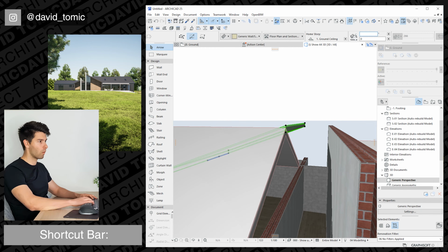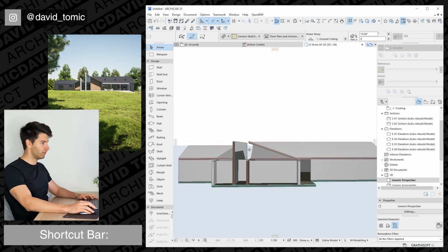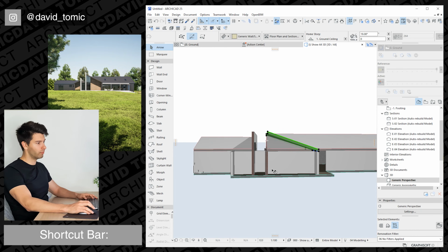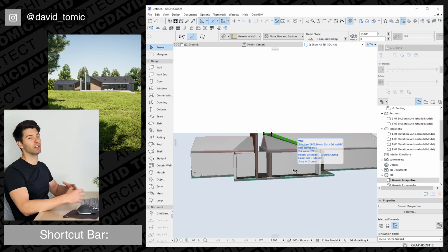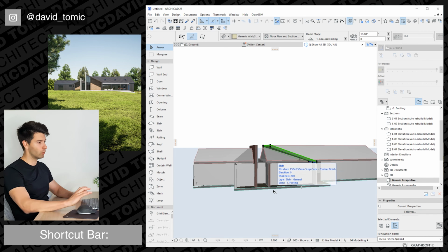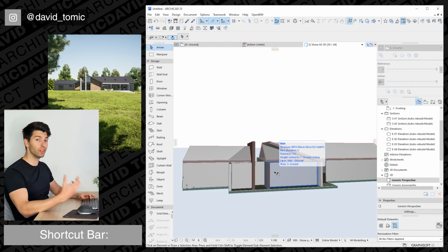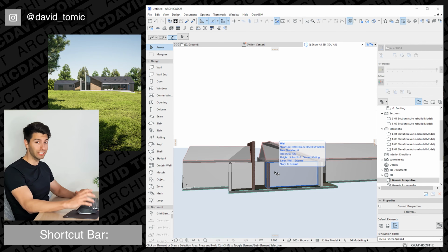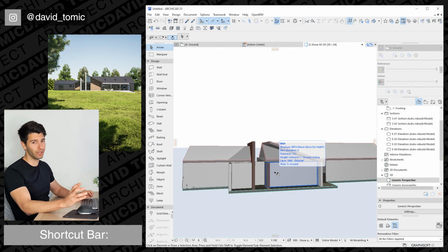And if I drop that 1 more degree, let's call it 19 degrees, that'll be a near perfect connection at the top. We would obviously do that in actual roof pitching degrees instead of just randomly selecting. But for the purposes of this, knowing that it's going to go everywhere around the world, there are all sorts of different construction standards that it would be just way too hard to get into. So we're just keeping things relatively generic. Make sure that you apply your construction guides, your construction knowledge, and your industry regulations to whatever you do design, because what you see on YouTube doesn't mean it can actually be built.